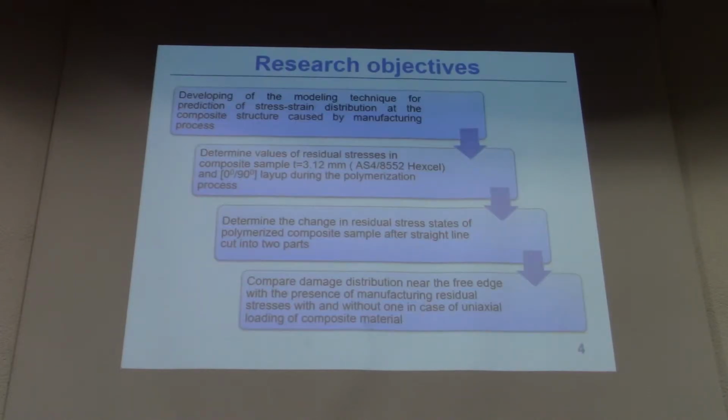So it's a nice thing that composites, speaking in common, are not like metals. If in metals we can provide the relaxation of the residual stresses, in composites it's not so. You should think about this problem at the stage of the design of the composite.